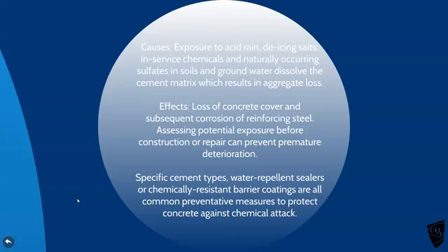It can diminish your aggregate if it's in there. It can actually eat away at it. The effect of it, you get a loss of concrete cover. You get bits of it spalling off and falling off. It allows corrosion of the reinforcing steel within it.